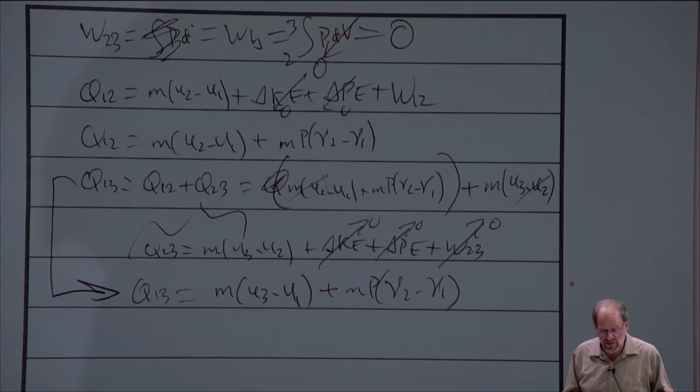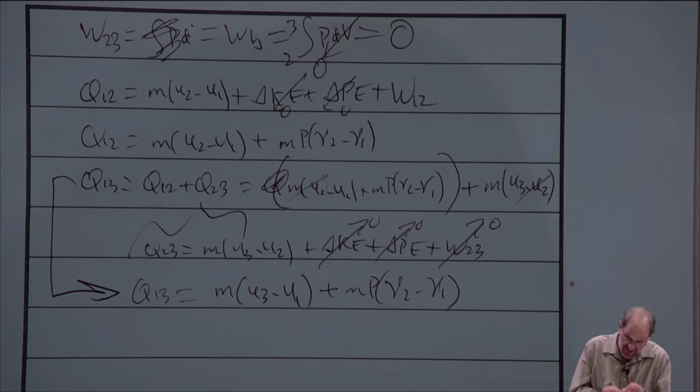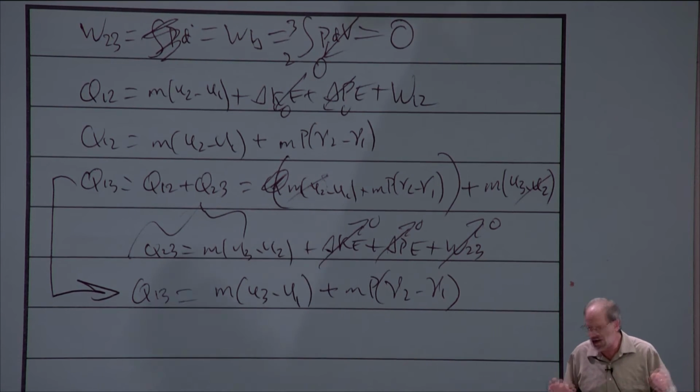And then what about at point 3? Well, we know that it's a constant volume process. So we know the specific volume at state point 2. That has to equal the specific volume at state point 3. So we know that information. And we're also told that the temperature at point 3 is 200 degrees Celsius. So again, we have two properties. We have volume and temperature, specific volume and temperature, I should say. Again, independent intensive properties, so state point 3 is known.